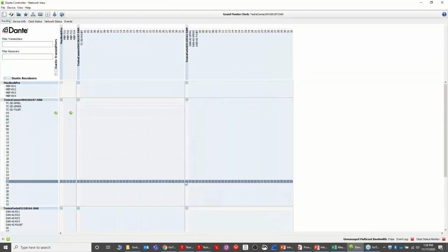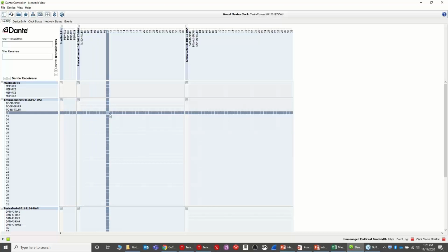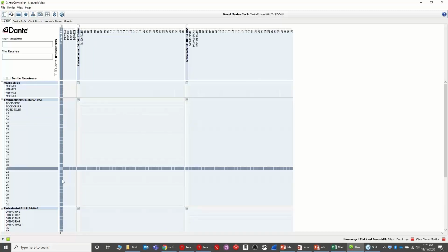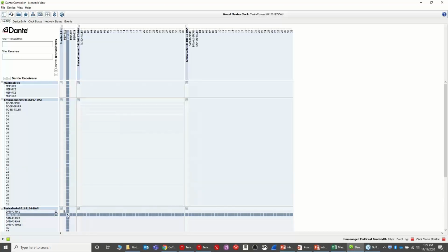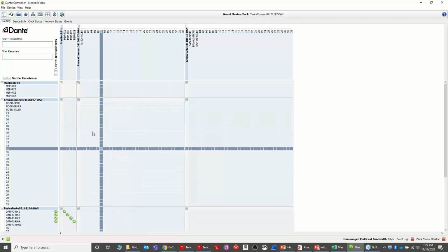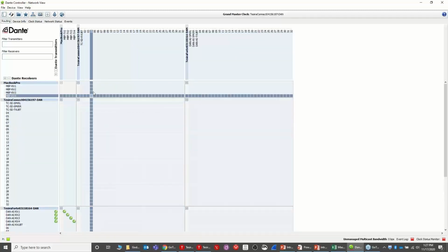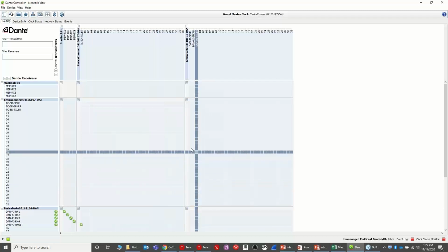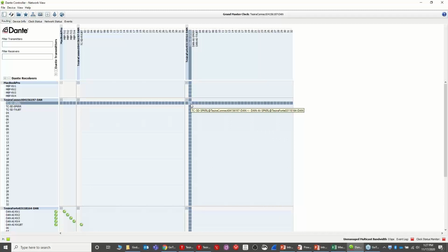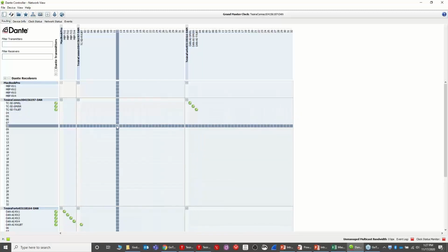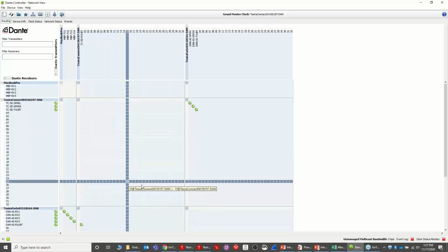So bring up Dante controller. So now we have to route the input wall plate, which is again being filled in for by this MacBook, and I will route that to my Dante receive channels in my Forte. Okay, I also need to have my Dante route for the EXUBT receive on the TesiraCONNECT. And that is going to be in my Forte as well. And then the last three routes I need to make are for the speaker outputs and the EXUBT transmit. And these are all from the Forte transmitting to the Connect. So 8 connections I needed to make there.